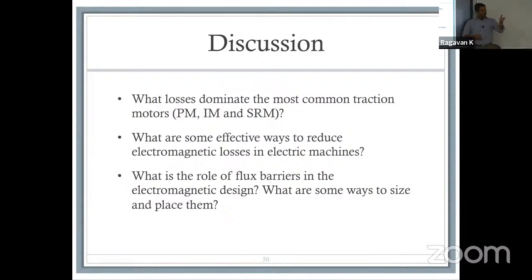And you're right. To start with the rotor core and start chipping away at the unnecessary parts, it's a very interesting idea. It makes perfect sense. It's not as easy as one would think, which is why you're getting a PhD out of it. But the idea itself is very practical. If you don't have that material being useful, you can eliminate it, because you're not only trying to use flux manipulators to shape your magnetic field, you're also trying to lower your weight.